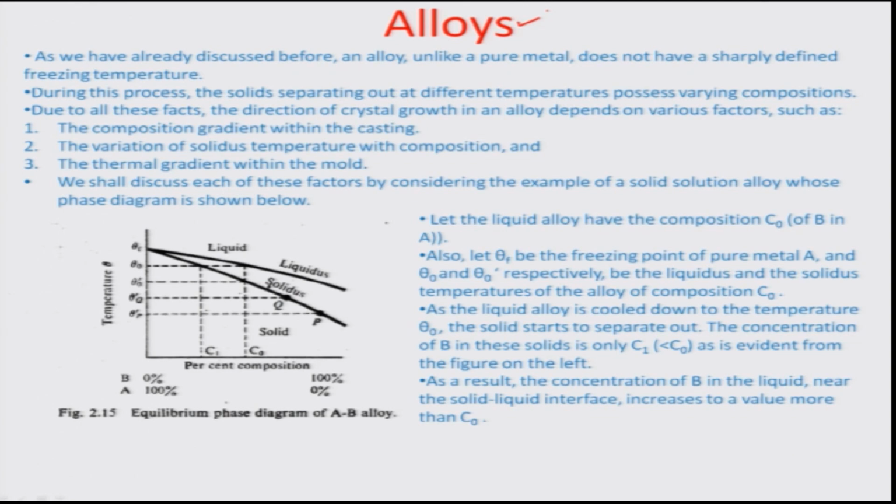Let us look at this particular case where there is an alloy between two phases A and B, which is 100% A along this particular line and 100% B along the other end, and there is a liquidus and a solidus temperature, beyond which the alloy would be completely liquid, and below which there would be a solid plus liquid phase, which is present also in this particular zone, and below the solidus line there would be solid phase present. So that is how you have arrayed this.